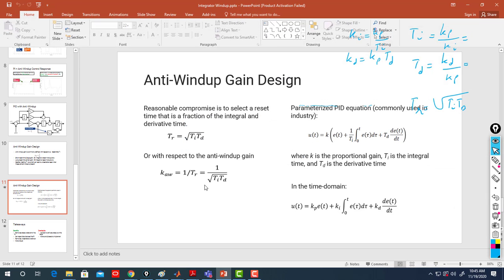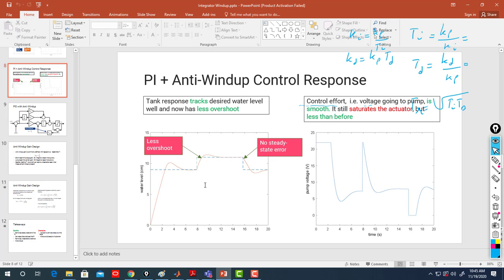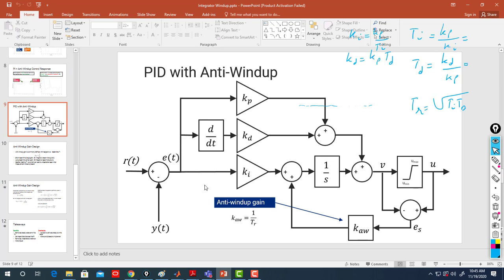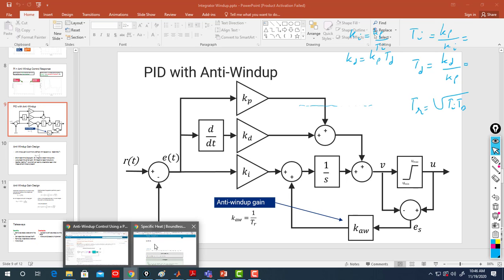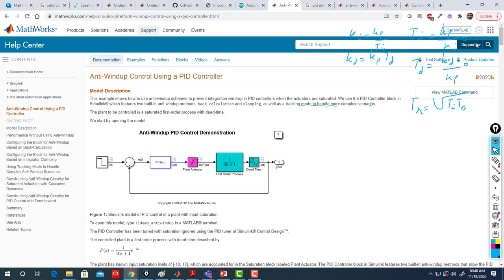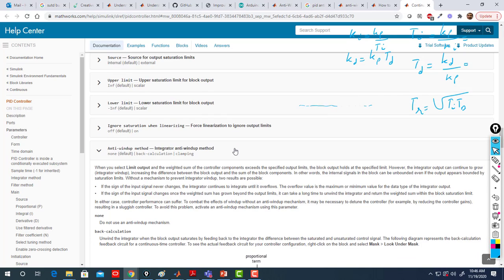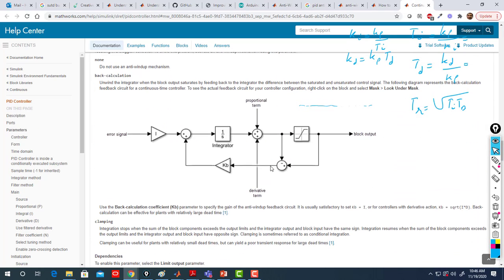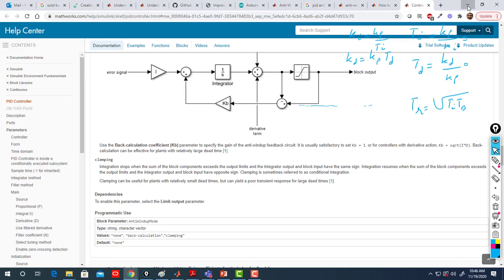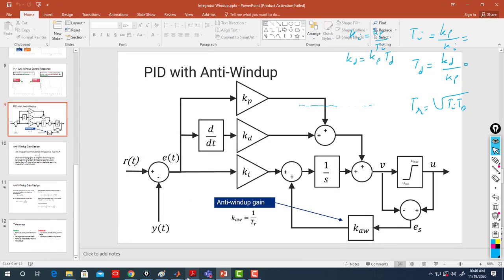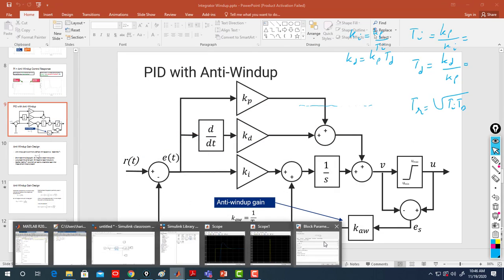Just to clear the effect of integral in reality and how we tune it, we need to implement the anti-windup effect, which is implemented for you in MATLAB in here, or the clamping method. So you can do the clamping. The clamping, if you want to do it quickly, just take 1 minute, guys.